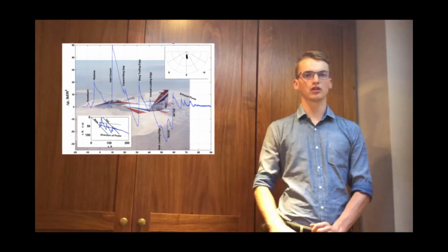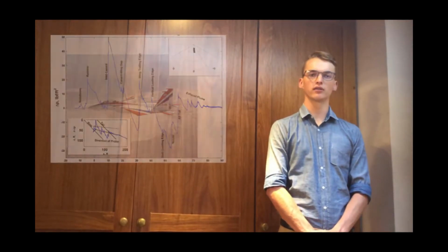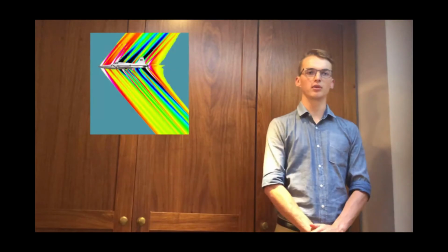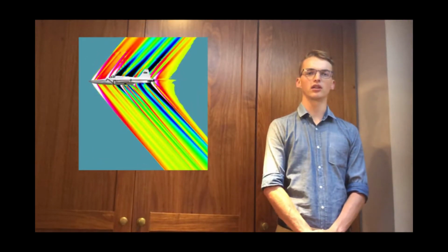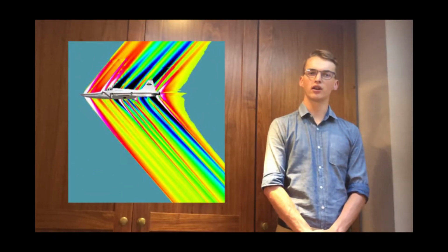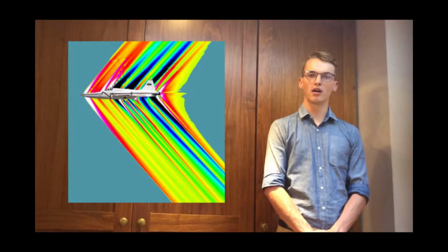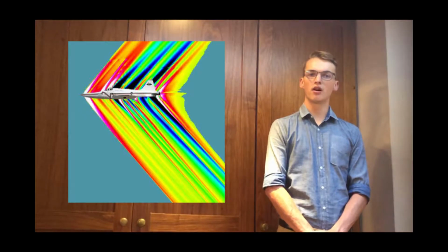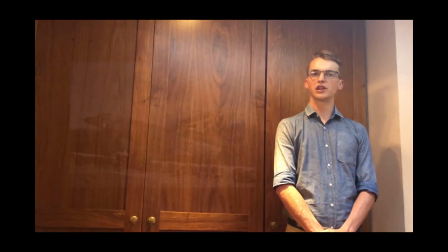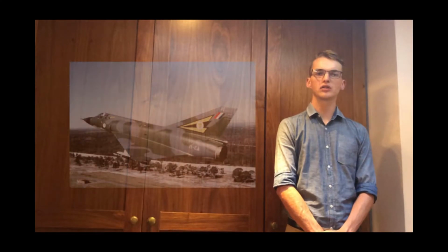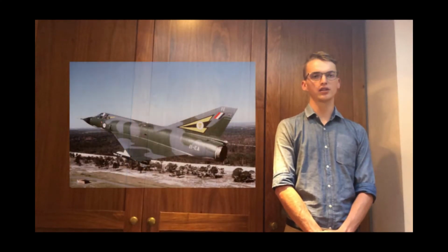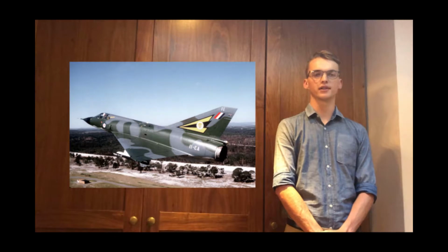This graph here shows the near-field pressure signature of an aircraft. This very colourful image shows the research NASA has completed in this regard by shaping an F-5 aircraft to reduce its ground shock signature. What should also become immediately apparent is the great complexity of the flow field around an aircraft. Due to this complexity, the typical approach used in gas dynamics research is one of reductionism. This essentially involves breaking a problem down into its fundamental parts and analyzing these already complex flow fields in isolation.